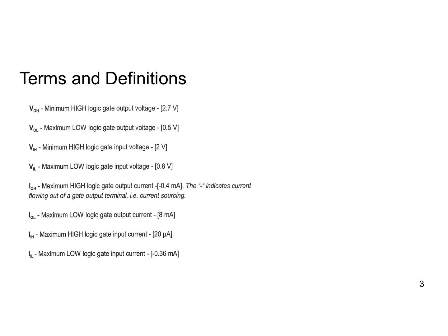Now, if you recall back to experiment 2, we used an LED, for the first time, in a current sinking arrangement. The reason is the LED itself requires more than the 0.4 milliamps in order to turn it on, which is why you cannot drive an LED directly with an LS series gate at the anode terminal.